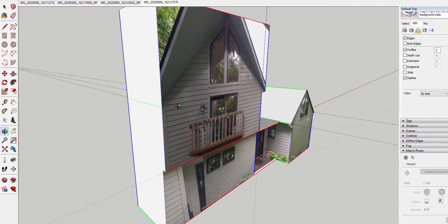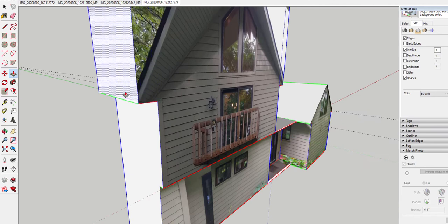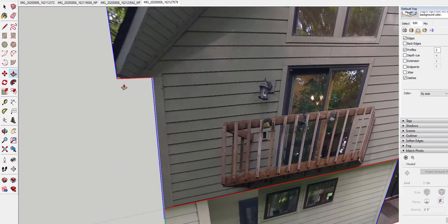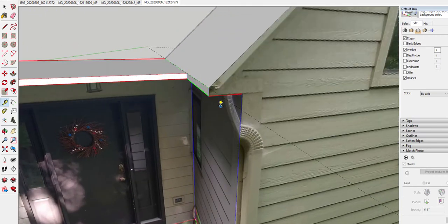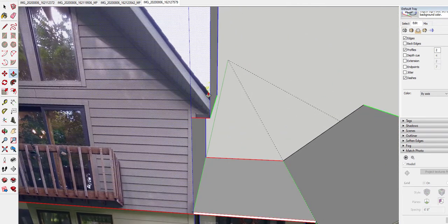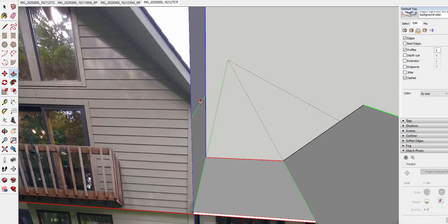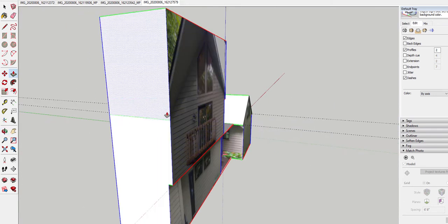And that looks pretty good, actually. Wow, that's pretty good. I'm going to go out from here out. I'm going to go out as well. Now, this looks like the same kind of overhang. So this was, you know, a 9-inch overhang. So I'm going to go ahead and push pull this back and then go out 9. Push pull this back, go out 9.